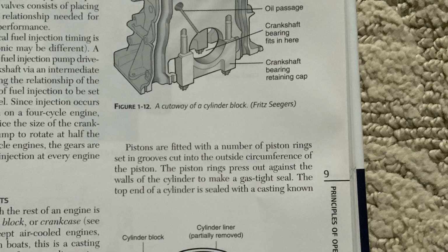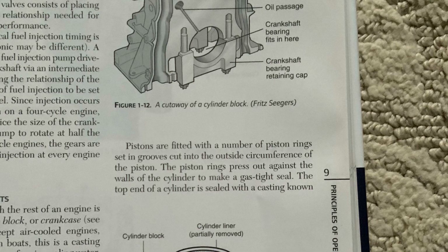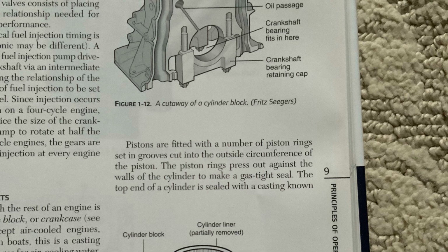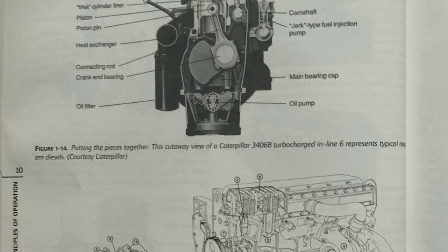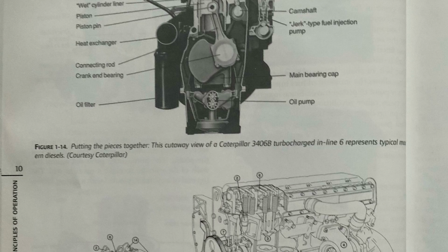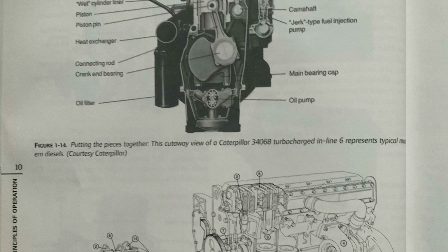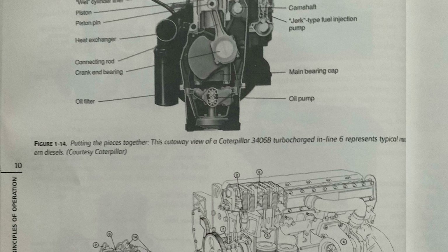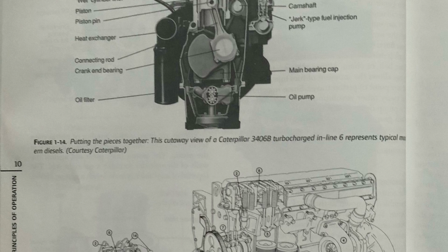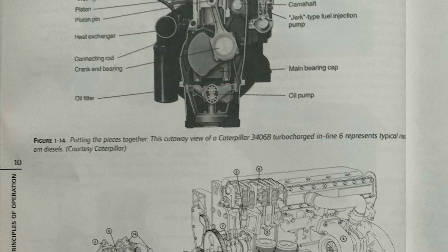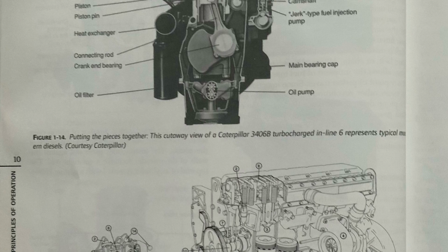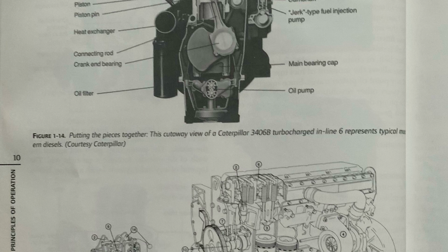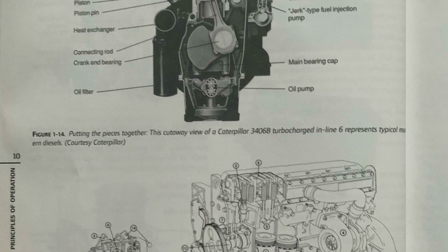There are two types of cylinders or liners available for diesel engines: dry liners and wet liners. In a dry liner diesel, the cylinders and block are in continuous metal-to-metal contact. In a wet liner arrangement, the block comes into contact with the cylinders only at the tops and bottoms. The engine cooling water circulates directly around the liners. See Figures 1-12 and 1-13.